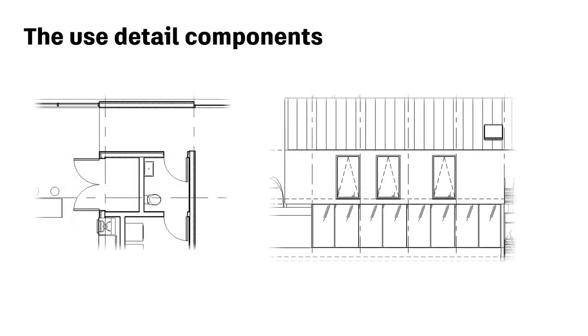As well as providing accurate construction information in detailed drawings, detail components can also be used to represent symbolic information relating to components such as door swings, glass, and window hinge positions in plan and elevation. These sorts of details are not necessarily derived from 3D models, but are needed for suitable construction drawings and details. The use of nested detail components negates the need to embellish Revit views with manual line work.